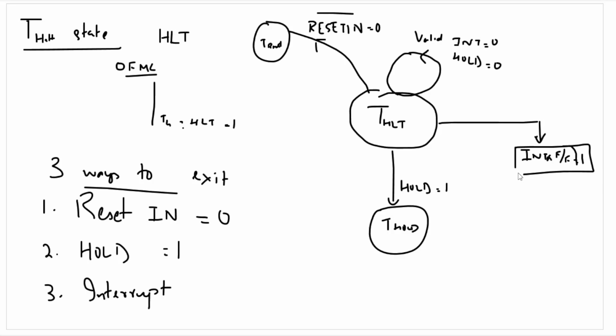And during the time the microprocessor is in this halt state, there's actually nothing that the microprocessor does. It's actually in the idle condition. And the microprocessor will enter halt upon the execution of T1 of the next machine cycle.